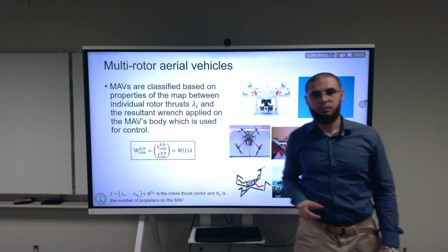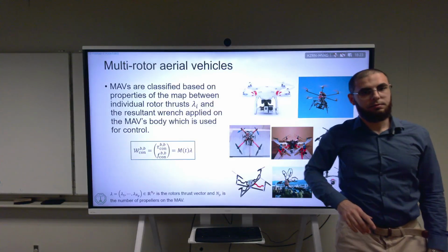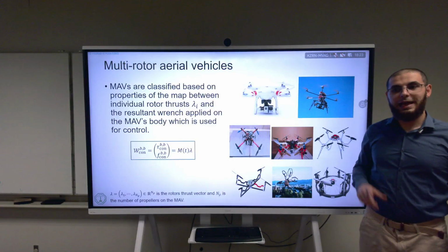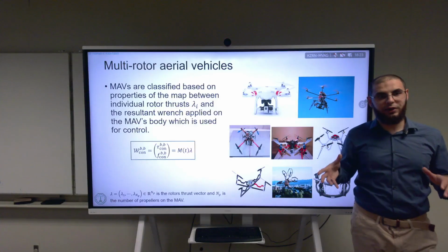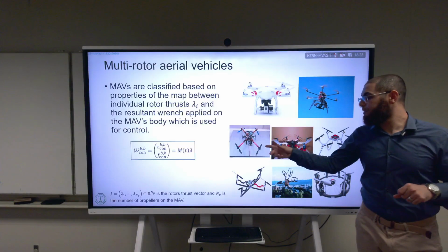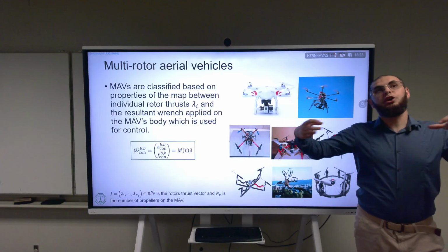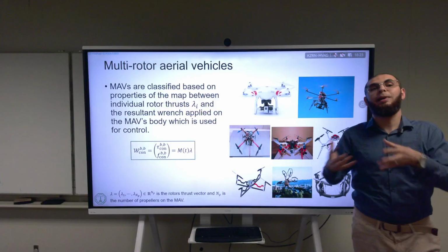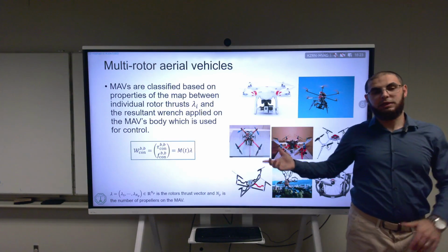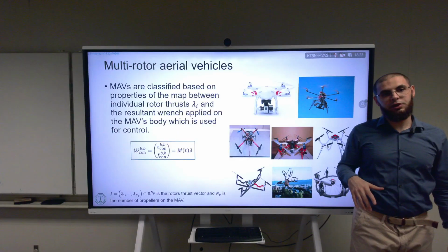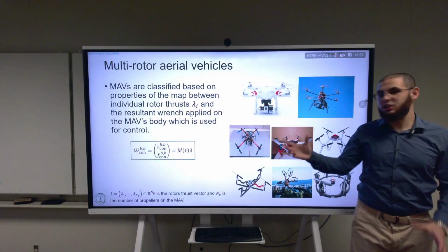Yes, Fahd. Going back to the idea of SE3, there are other vehicles that we cannot use SE3 for. Aerial vehicles, for example, where it's not enough to say it's SE3 as the configuration. If you have very big propellers, in other words, if the inertia of the propellers or the angular momentum of the propellers as they rotate is not negligible, then you cannot say, okay, it's just one rigid body. It doesn't have to do with the type of thing we're flying. No, it's just the scale.